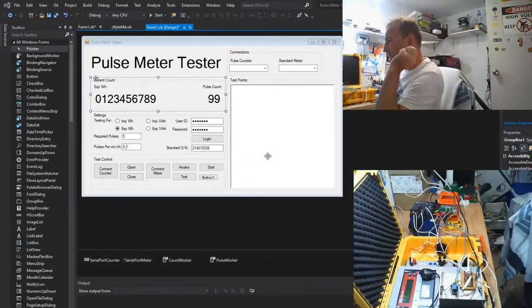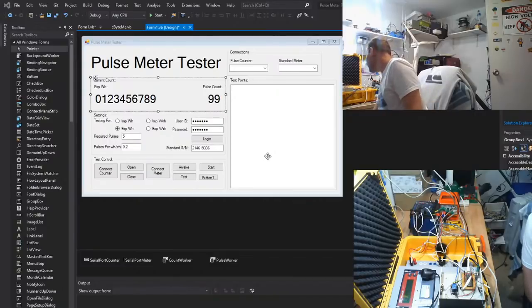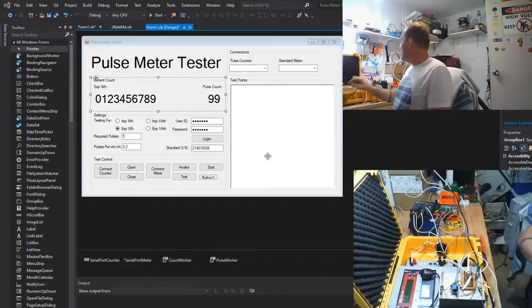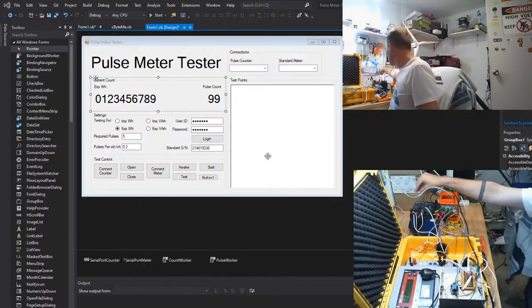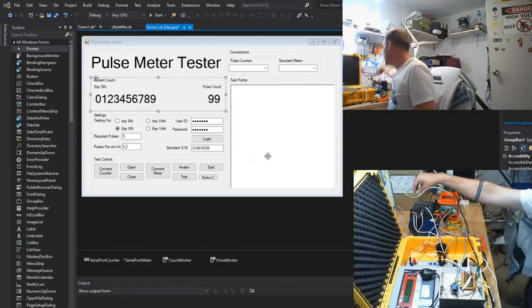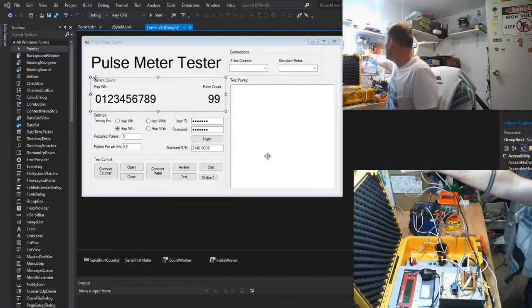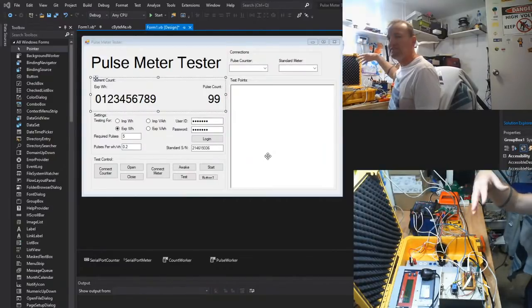Alright, so what I'm doing is I'm building a watt-hour calibrator and bar-hour calibrator. Sorry about the chair, it's squeaky. What that means is I'm looking at one meter against the other. I have 3 meters set up here. I've got a Radian Research RN11. I'm comparing that against a Mark 6E and also comparing against an EDMI Atlas Mark 10. And then I'm going to try and check them against each other.